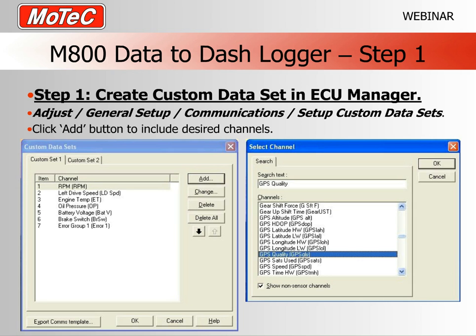So normally with that unchecked, you'll have a relatively small list, and it will show all of the inputs, for example, for speed, for AV inputs like position, manifold pressure, and also the AT and the switch inputs. So if you need to see the other data, for example GPS, make sure you have clicked on the checkbox at the bottom. And then you'll get quite a long scroll down list.